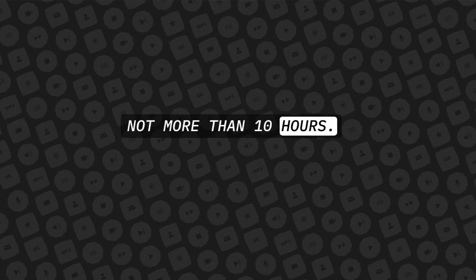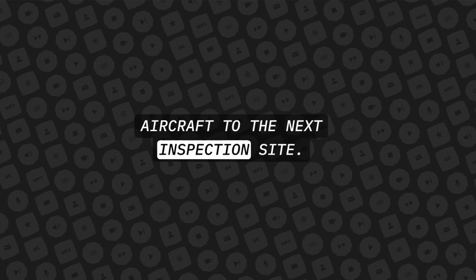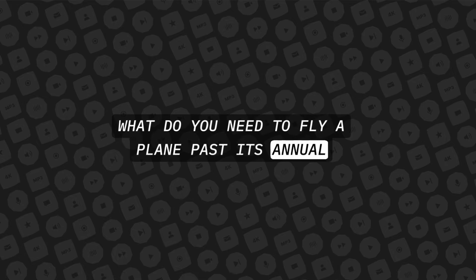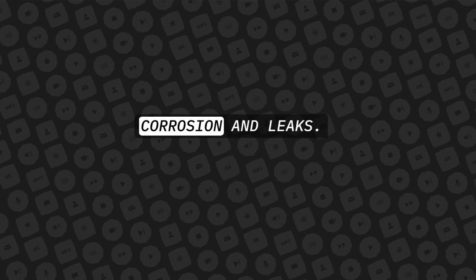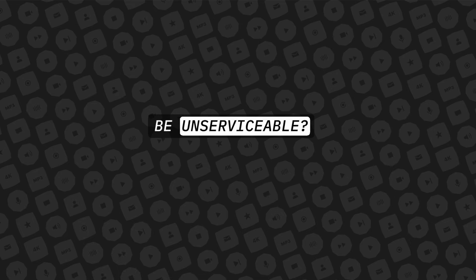Not more than 10 hours. The 10 hours may only be used to ferry the aircraft to the next inspection site. What do you need to fly a plane past its annual date? A ferry permit. What do you look for when inspecting floats on an airplane? Corrosion and leaks. What condition of an aircraft seatbelt would be unserviceable?